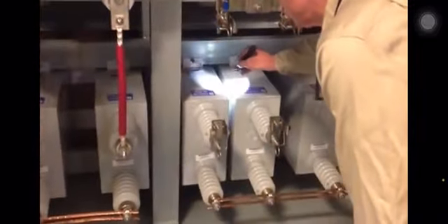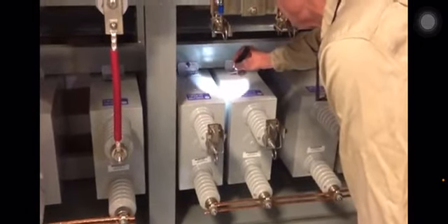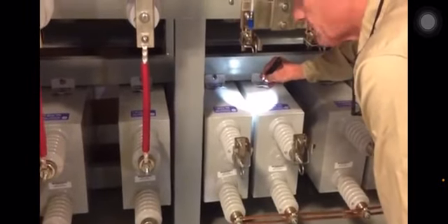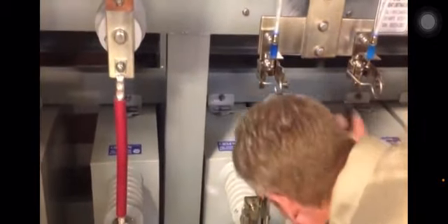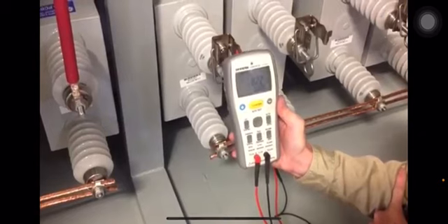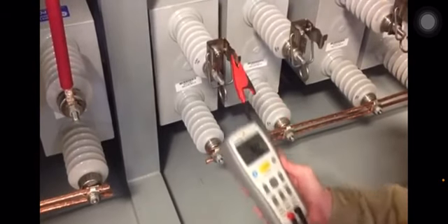This is a GE capacitor, and so there's an information plate riveted to the mounting bracket. If we look at that plate, there should be a value on that plate from the factory. And in fact, it reads 82.2 microfarads. So they in fact match exactly. So we know this capacitor is good.